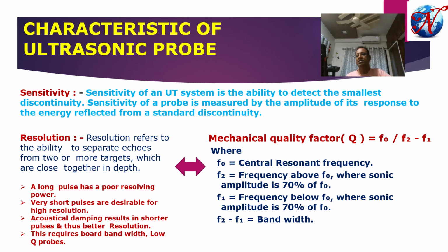Whenever the dB value is less, attenuation loss will be less, the signal to noise ratio will improve, and defects can be identified with very high accuracy. So a highly sensitive system and probe is always preferred.